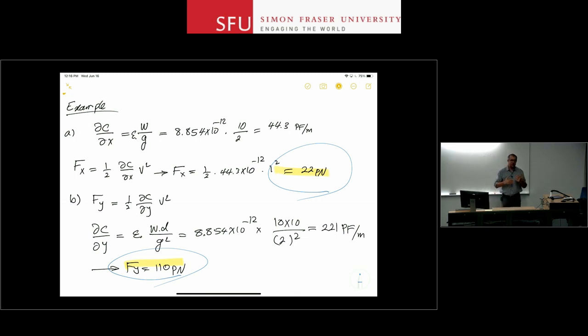The challenge here is that compared to CMOS, where everything is happening on the surface of the wafer, the challenge is only lithography. If you can put the drain and source of that MOSFET close to each other and separated from each other after the lithography step, you have solved the biggest problem in your challenge.